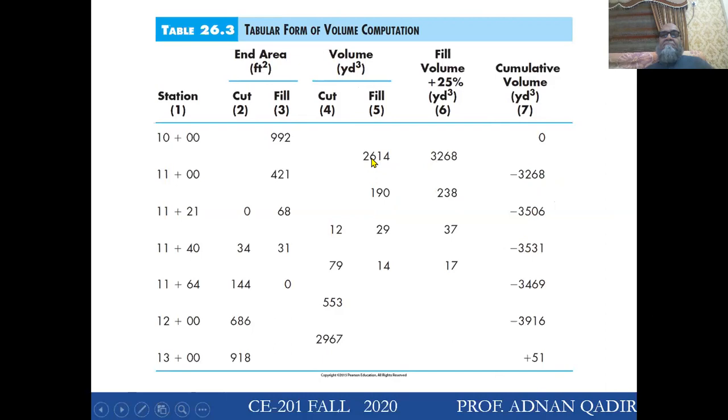And then this full volume. So actually, this will be a fill volume and a cut volume, and the actual fill volume is this, but the material that is required is to be this. So that's why when we say cumulative fill, we'll add these two values. So for me, this is first point 0. So 0 minus 3268 becomes minus 3268.